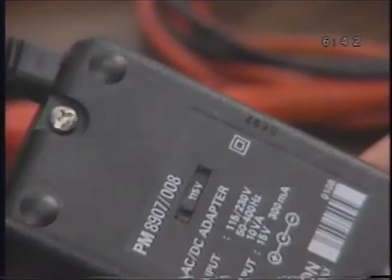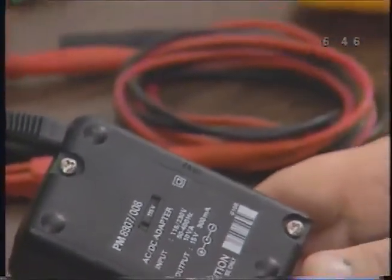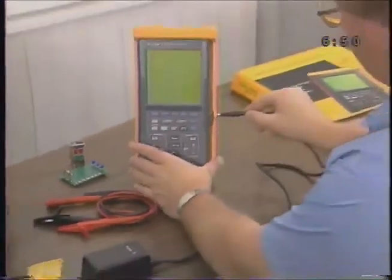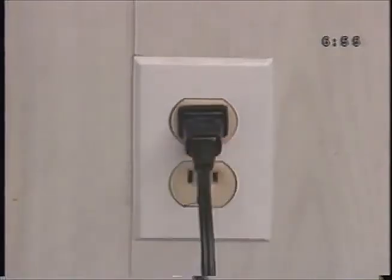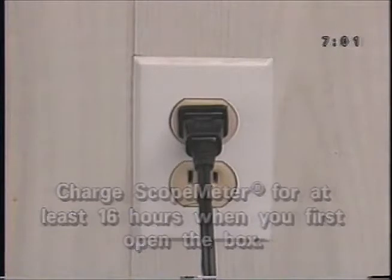To charge the batteries, or to operate your Scopemeter from standard AC current, make sure you set the charger to 115 volts. Plug the power adapter battery charger into the external power jack and a regular wall socket, and charge your Scopemeter for at least 16 hours when you first open the box to bring the batteries to a full charge.